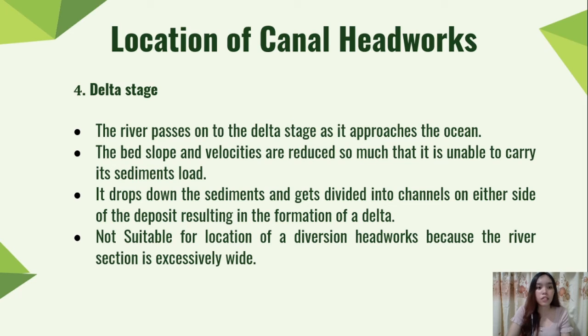And then the last stage is the delta stage. The river passes onto the delta stage as it approaches the ocean. The bed slope and velocity are reduced so much that it is unable to carry its sediment load. It drops down the sediments and gets divided into channels on either side of the deposit, resulting in the formation of a delta. The delta stage is not suitable for the location of a diversion headworks because the river section is excessively wide.